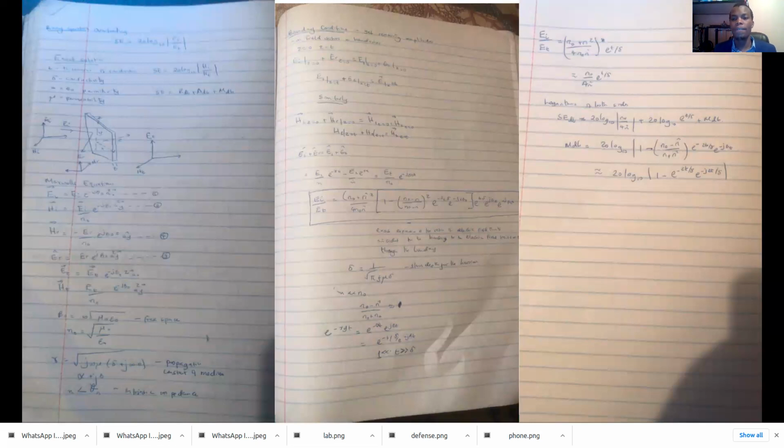But remember, we are having three parts of this formula. We were having R in dB, which is the reflected component. Then there is the absorption, so the reflection losses, the absorption losses, and the multiple reflection losses. So you can be able to derive them by replacing the values there, and getting to know something called skin depth, which is delta, which is an inverse of the square root of pi f mu sigma.